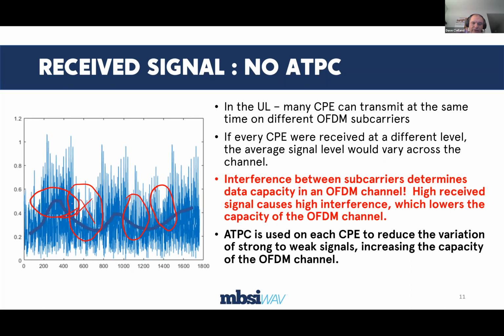So if this were a whole series of subscriber modules, like in our example where we had the 3, then it's possible that if there's a subscriber module in here that is having to retransmit, and the same thing here and here, these could be bad enough that they're dropping the modulation level and retransmitting. All sorts of terrible things are going on here on this channel that are wasting time and bandwidth in the channel.